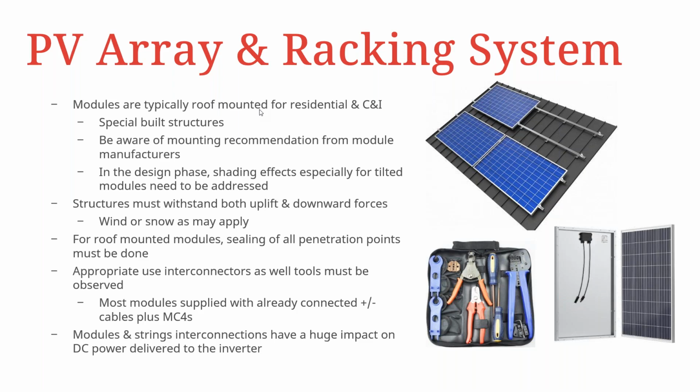Most modules are supplied already with MC4 connectors on the positive and negative side, and the modules and string interconnections have a huge impact on the DC power delivered to the inverter. If you've got a faulty connection plug, for example, you'll see a derate of that string, or an isolation error would occur if a DC connector, MC4 connector, apologies, is not connected properly.